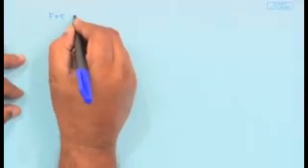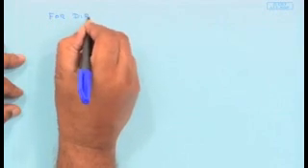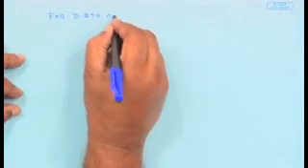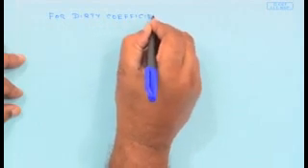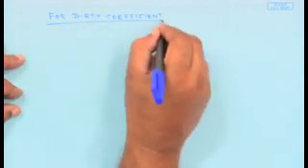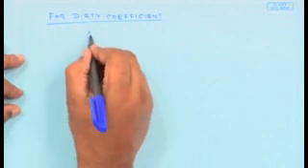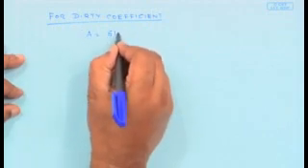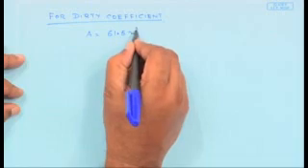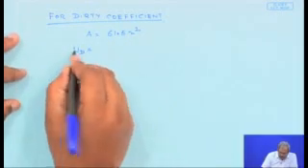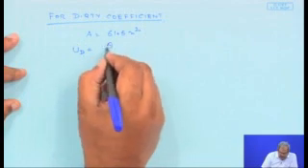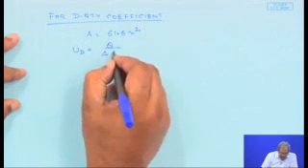So in order to calculate the dirty coefficient, I know that my value of the heat transfer area provided is 61.5. So UD, the dirty heat transfer coefficient, is Q by A delta T,